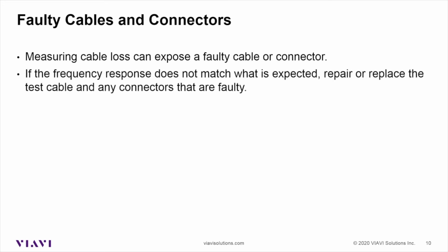If we are measuring transmit power, we'll see that roll off sometimes. We'll be able to look at that and go, well, at this frequency, power was good. At this frequency, power was okay. By the time we get to this other frequency over here, it's way low. Sometimes it doesn't show up there. Sometimes we're able to make alignments and make up for it. So we went through the auto test or the cable loss measurement on the 8800 there. We can also go out to the web and look up the specs for a cable, and we can calculate what the loss should be. And that is typically pretty close.